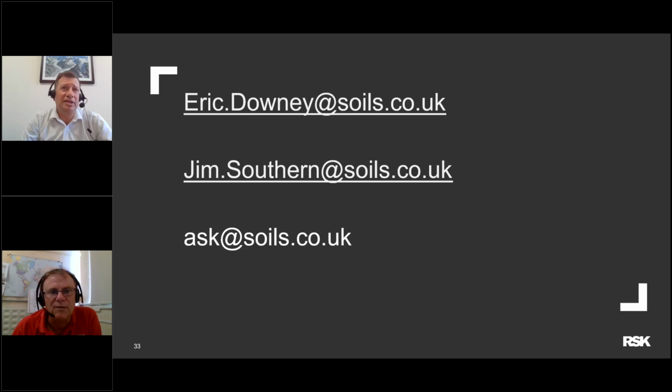Yeah, I did this some time ago on the A2 in Blackheath, and we used microgravity to look for voids basically. The A2 disappeared into a big hole, and they wanted to make sure that the A2 was not full of holes. So we definitely used microgravity as one of them. We used cross-hole seismics for others. So geophysics in conjunction with the ground investigation itself is probably the best way forward.